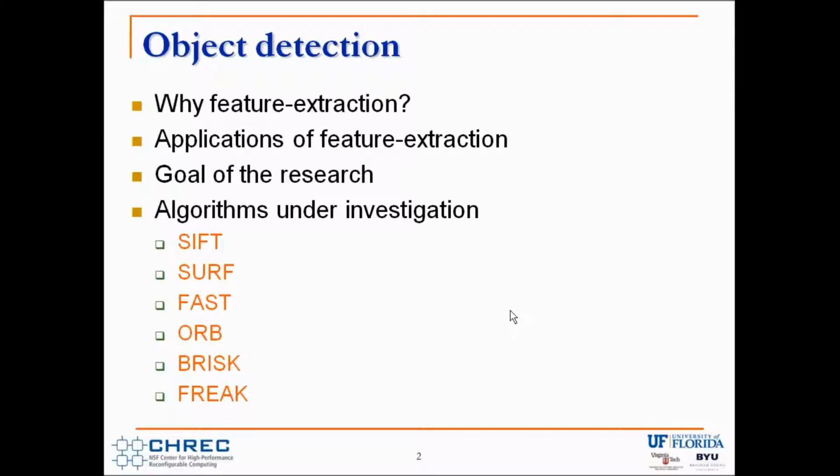For a given feature extraction algorithm, several performance parameters must be taken into consideration and the design space for a given system should be explored to attain the optimal performance. The design parameters affecting the performance of the kernels are affine transformation, scale, orientation, illumination, and blurring. A change in these parameters results in loss of features, affecting the object matching algorithm, as the features of the object play a major role in extracting the information.